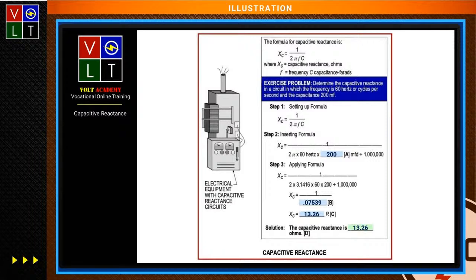Right. Therefore, if the frequency increases, the capacitor charges and discharges more times per second. Therefore, that means more current does what? Flow in the circuit. Yep. Okay. Now, just to combine that, what does that really mean? It means reactance decreases as capacitance or frequency increases.